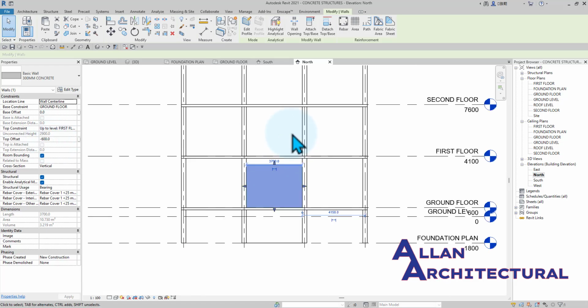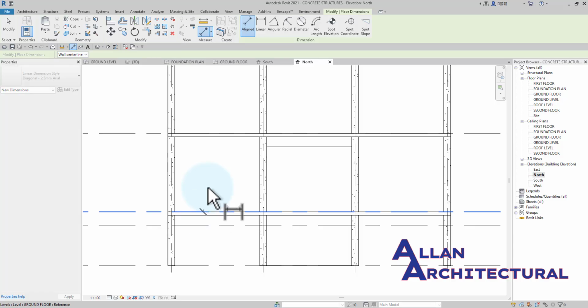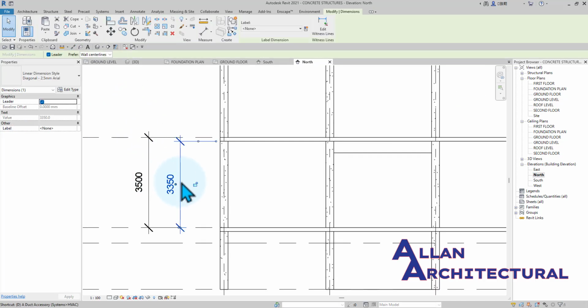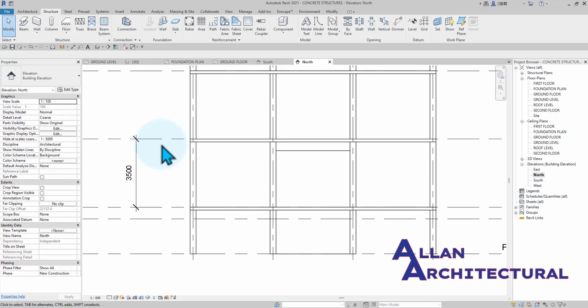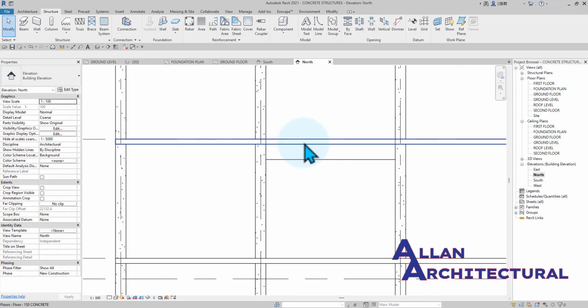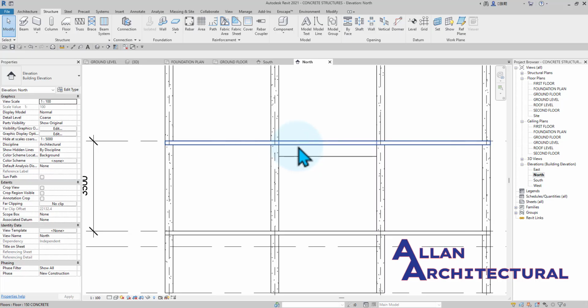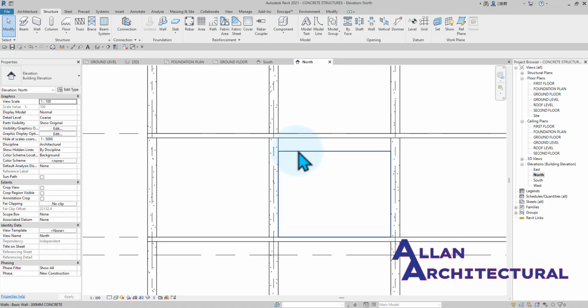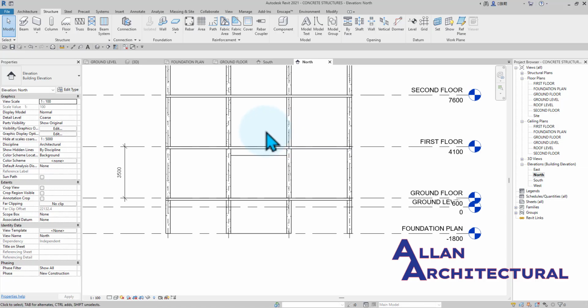We have our top constraint in there, and let me just measure what I have in here from this level. Oh, okay, so we have 3,350, and we have this at 350, and this going at 350 as well. So this is perfect. We've already eaten into this dimension, which is the 150 for the floor slab in there. So we need to now place in our, let's say 150, so we can do a beam which is going to extend about 350 downwards in there. Now let's start off by placing in our beams.